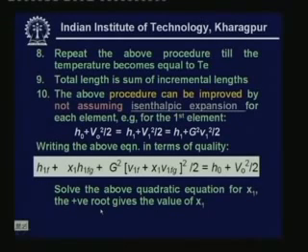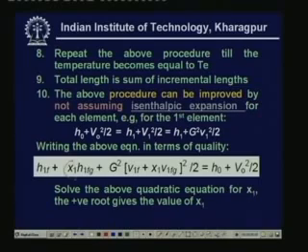So you can improve, as I said, the above procedure by considering a non-isenthalpic expansion. That means we write the energy equation also, in addition to the mass and momentum equations, like this: H naught plus V naught square by 2 is equal to H1 plus V1 square by 2, and replace V1 by mass velocity G and specific volume V1. And that equation is written in terms of the dryness fraction X1.